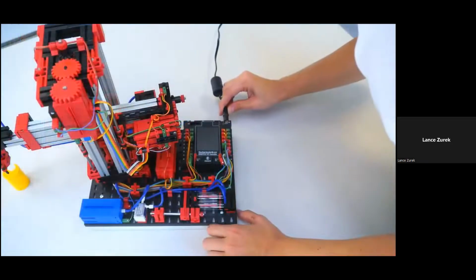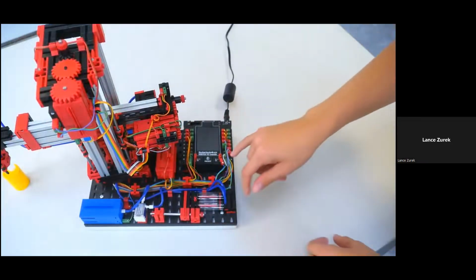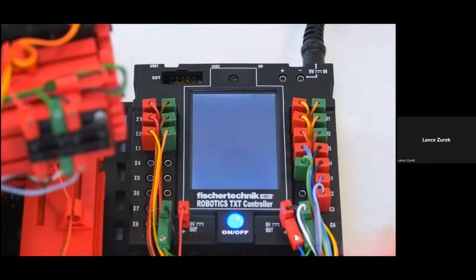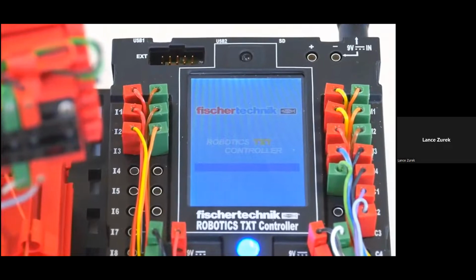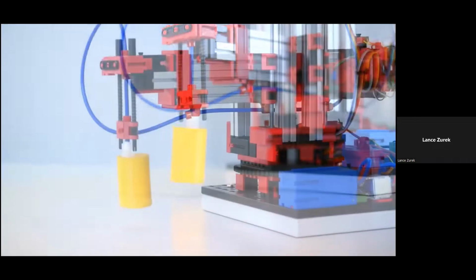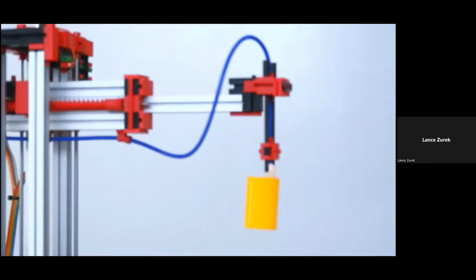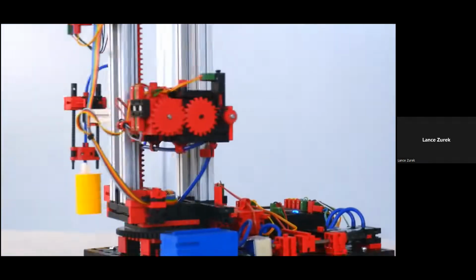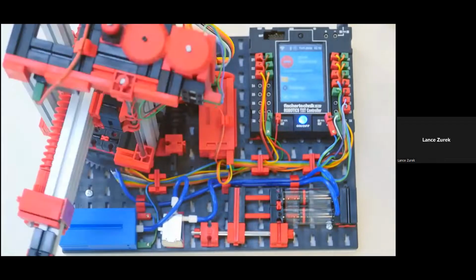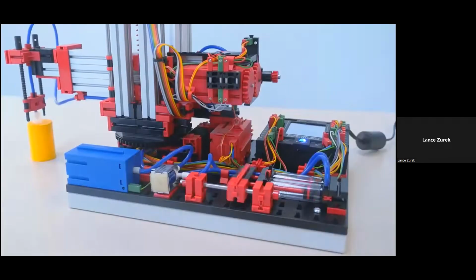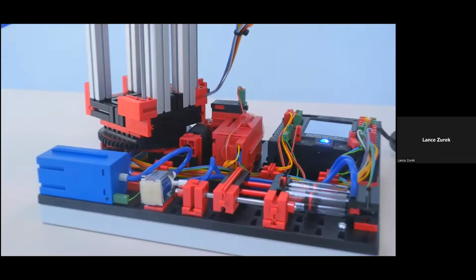The 24-volt versions of this model, currently the only ones available, as well as all the 24-volt versions of the first 5 models we're going to look at, each has a relay board for motor polarity reversal and both a multi-pin connector with 34 pins and a grid of 2.54 millimeters, as well as additional PCB terminals with push-in connections for all inputs and outputs.